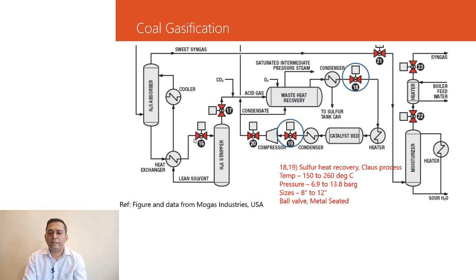Here 18 and 19, the temperature is 150 to 200 degrees centigrade. Pressure is same. Size is 18 to 12 inch, and here also a ball valve with metal seated is required.